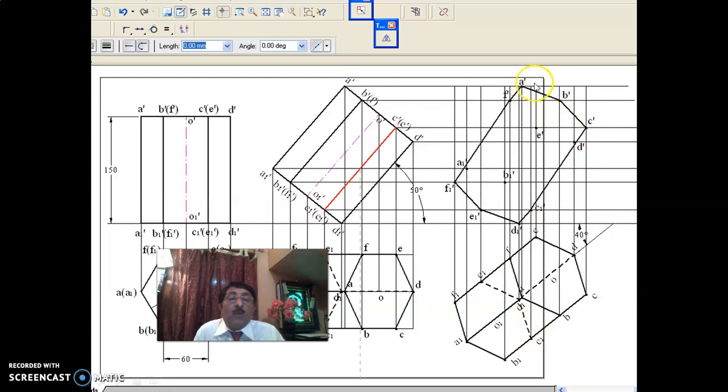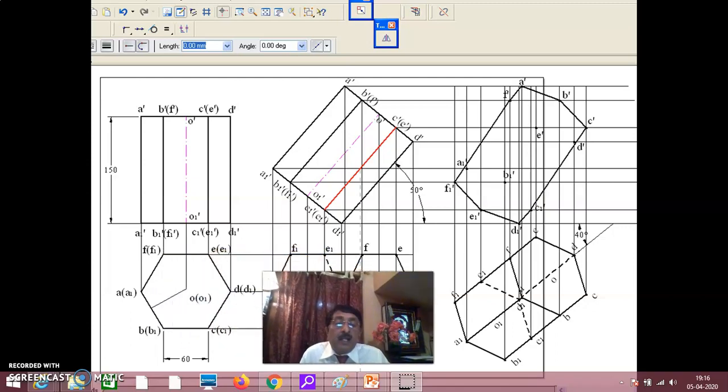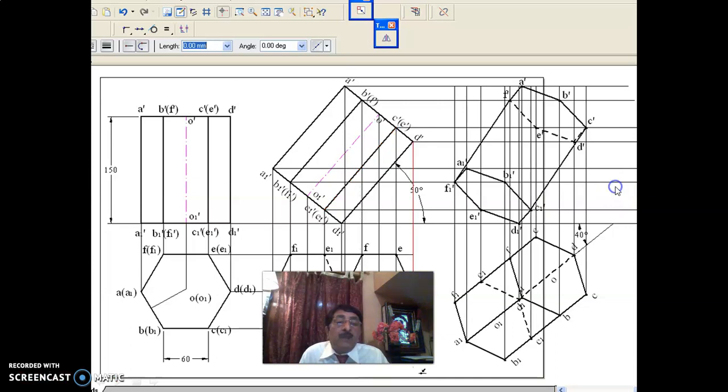Now you see here, once the outer boundary is over, you are looking from here, so the bottom surface is nearer. Darken the bottom surface, and immediately make the remaining edges of the top surface dark dotted. See here, this is the bottom surface, you darken it, and the remaining edges of the other surface are made dark dotted. Now carefully you see here.